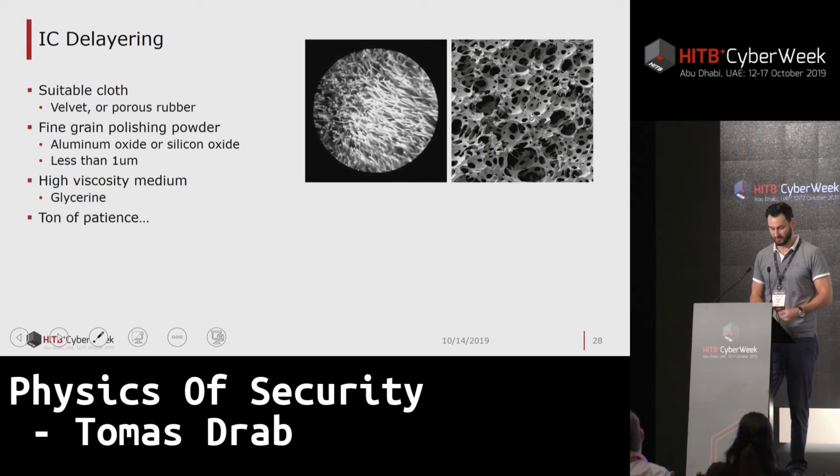All you need is some hairy cloth like velvet, which can hold some medium. You need some grinding material, like really fine grain powder, like aluminum oxide or silicon oxide, and some high viscosity medium, like glycerin, and I think olive oil would also work.